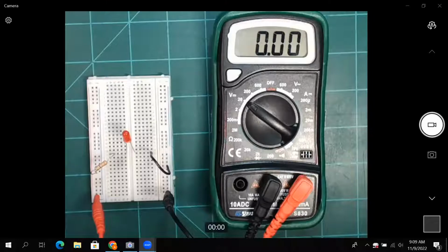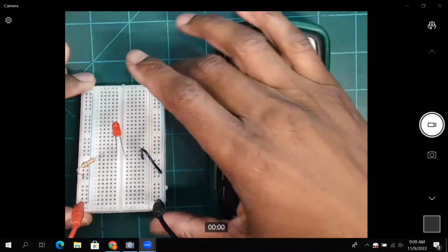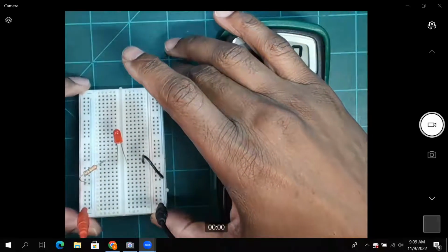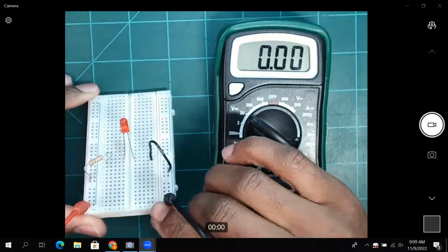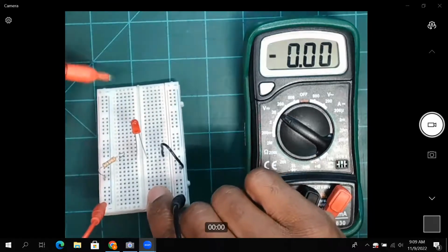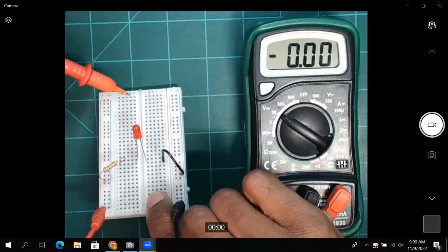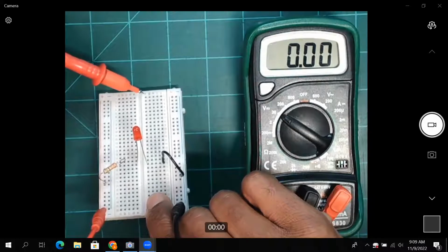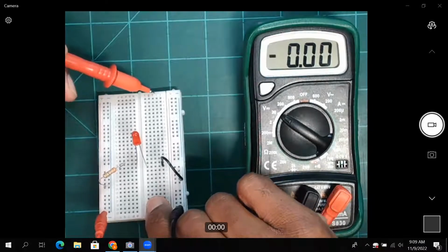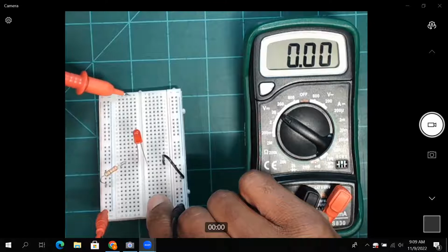Firstly, let's talk about how to use a multimeter. So just to recap, here is my breadboard. We went over breadboarding in our last class meeting, so let's take a really quick recap on how a breadboard is wired. A breadboard has pins which connect column rows A, B, C, and D, and there's another pin that connects F, G, H, I, and J. Notice you have these columns A through E and F through J.